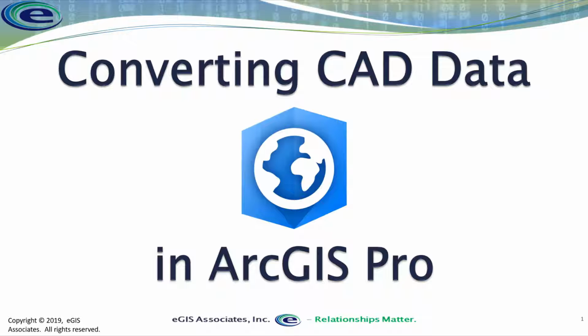Once we get it georeferenced, though, if we actually want to do something with it, oftentimes we need to convert it from that CAD format, that DWG or DXF or DGN file, into a GIS-friendly format like a geodatabase feature class or a shapefile or something along that line. And so that's what we'll talk about here in this video. We're going to see what tools are available in Pro that will allow us to take data that's in a CAD format and put it into our GIS.